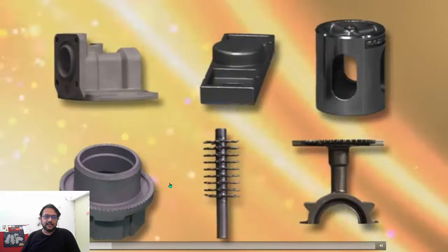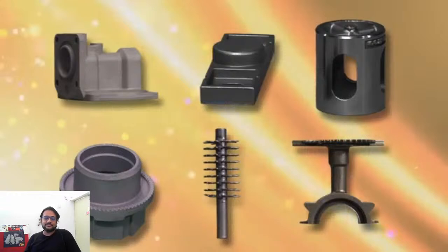So as you can see, in traditional casting processes it would be nearly impossible to cast this in, let's say, steel, only because these features are quite thin for a process like sand casting to work. The other thing, if you notice carefully, is that there is a significant amount of undercuts. I will not explain undercuts, I think you should know. Undercuts are places where you would probably need a core to get features like that.